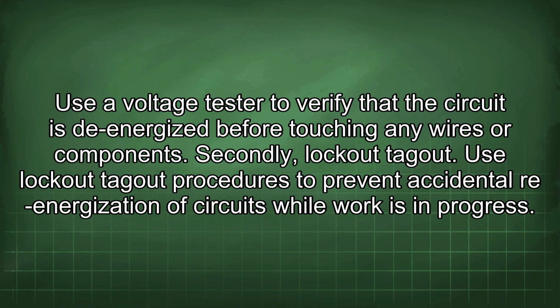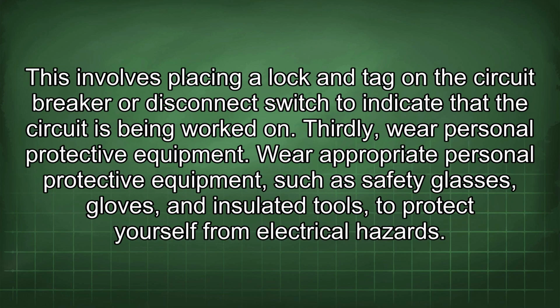Secondly, lockout-tagout. Use lockout-tagout procedures to prevent accidental re-energization of circuits while work is in progress. This involves placing a lock and tag on the circuit breaker or disconnect switch to indicate that the circuit is being worked on. Thirdly, wear personal protective equipment.